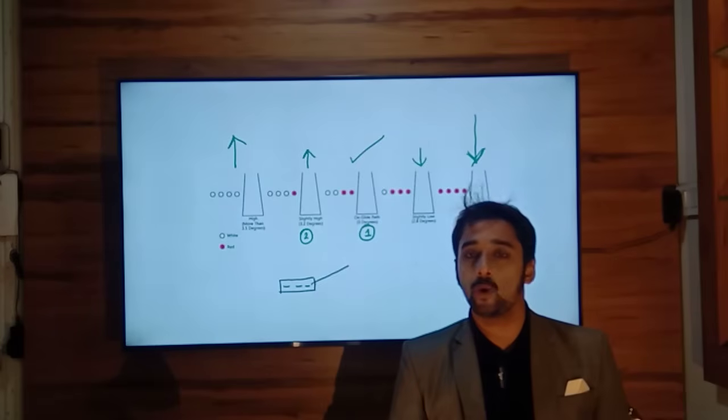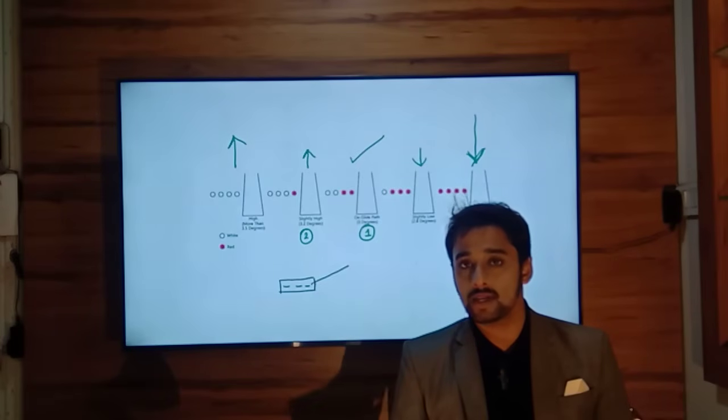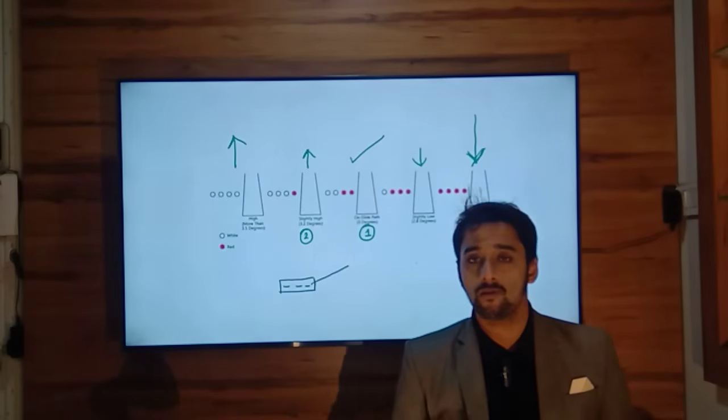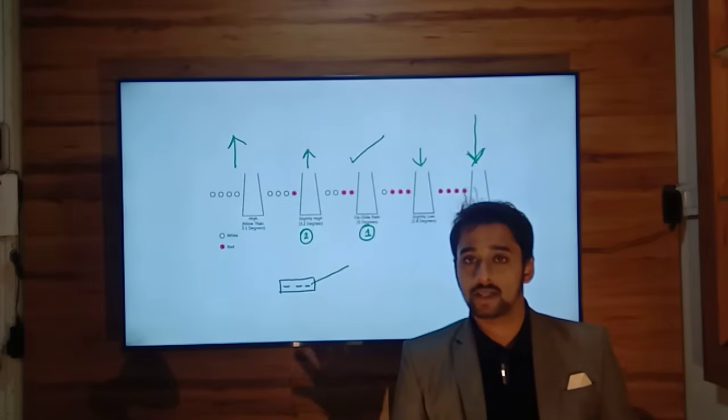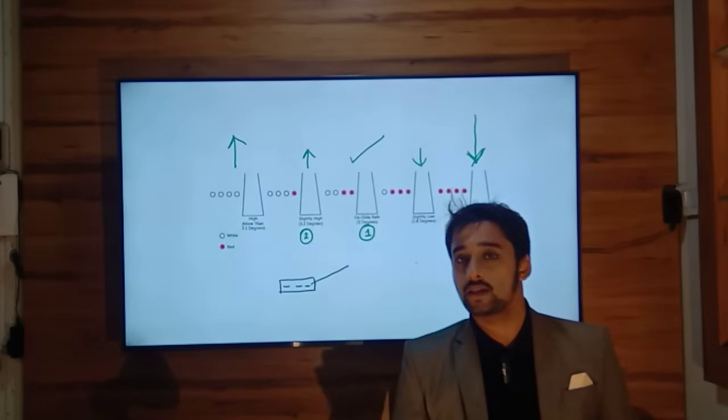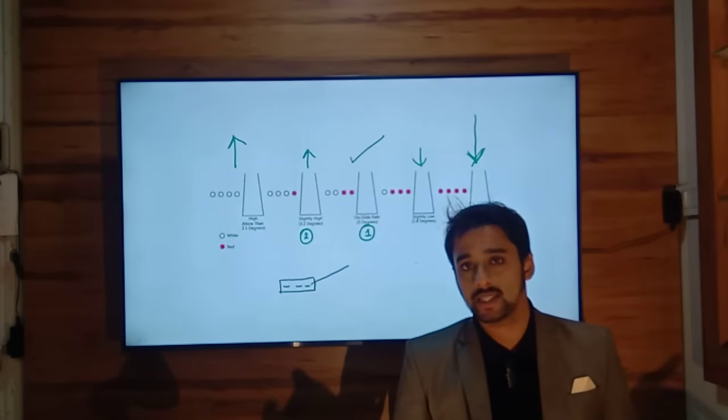Whether they have onboard radio navigation equipment like ILS or not, PAPI lights are an all-weather gadget available at the airport, but you should be VFR. In case you are flying IFR, you don't need PAPI lights as such.